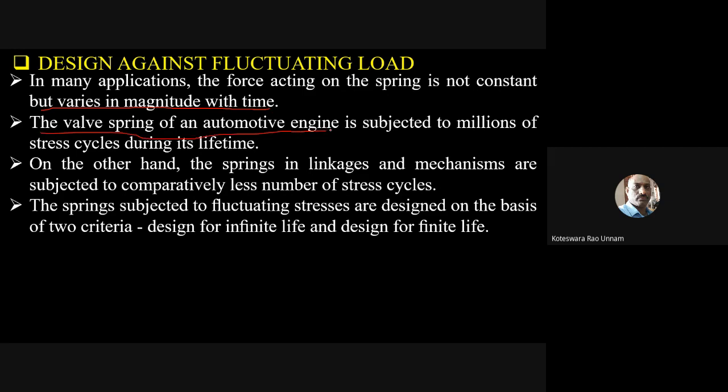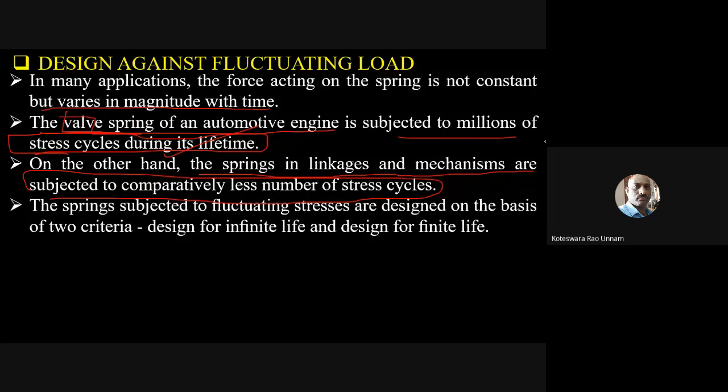The valve spring of an automobile engine is subjected to millions of stress cycles during its lifetime. Therefore it is subjected to a fatigue load. On the other hand, the springs in linkages and mechanisms are subjected to comparatively fewer stress cycles. So suppose you are using a spring to operate a valve, it is subjected to millions of stress cycles, which means you need to design this spring for infinite life.